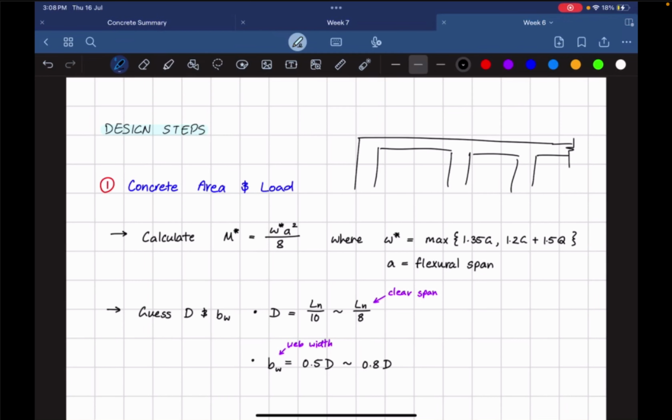Normally you'll take the maximum span, the greatest span, because your greatest span is going to be your most critical one. What that means is the longer the span, the more prone it is to failing, which makes sense. If I take my student card like this and squish it this way, or apply a load to it, it's a bit more stiff. It doesn't bend as much. However, like this, it bends a lot more. Think about a ruler now. It's going to bend way more.